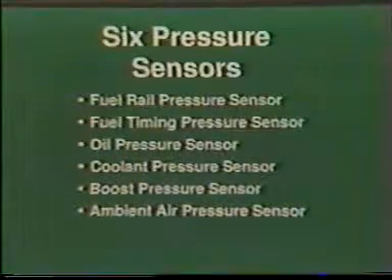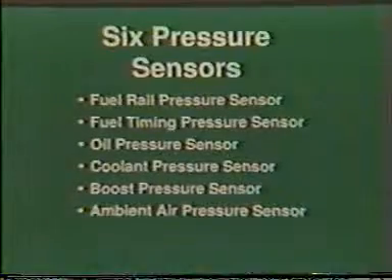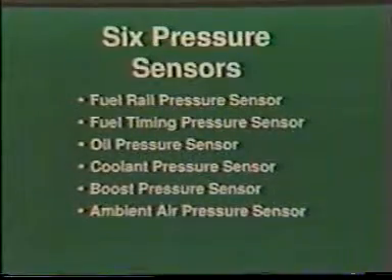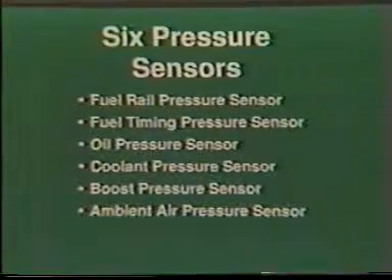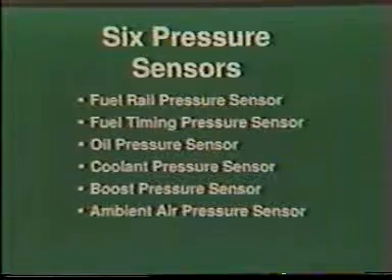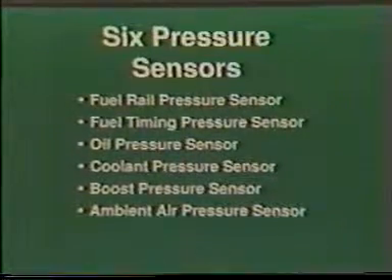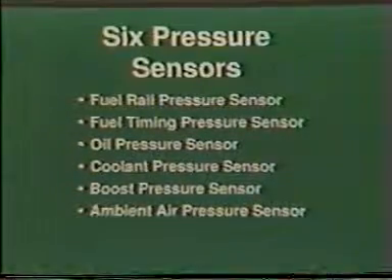There are 6 pressure sensors that provide critical information to the ECM. The pressure sensors are the fuel rail pressure sensor, fuel timing pressure sensor, oil pressure sensor, coolant pressure sensor, boost pressure sensor, and ambient air pressure sensor.